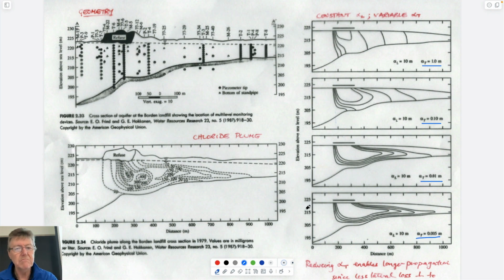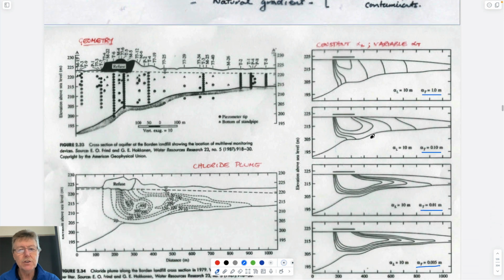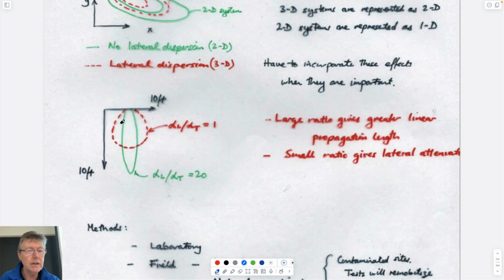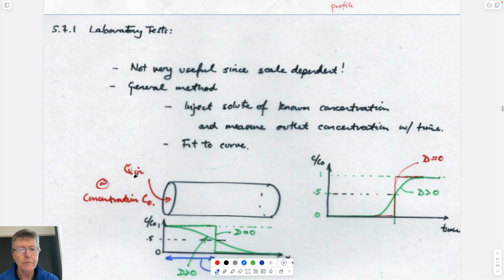And you can rationalize it. It's the same rationalization as we're applying here. Physically, by changing the coefficient of the transverse dispersion, limiting it so it doesn't transversely disperse, in other words, so it looks like the green curve instead of the red curve, then you increase the concentration of the stuff that's trapped within the section. So, a straightforward point.